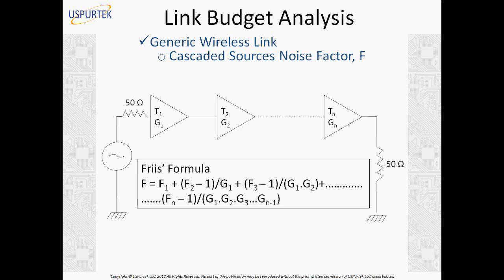That is why, in satellite communication equipment, you must have seen they always put a low noise amplifier, LNA or LNB, on the dish itself, because that improves your signal to noise ratio by a big factor. You don't need a very high-end amplifier on the last stage, the power amplifier, but the LNA must be very good. That is because of this equation here. The front end is the biggest contributor to the noise factor, so the amplifier at the front end must be the best one.